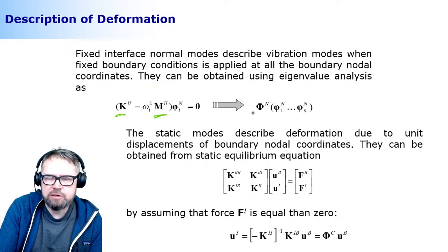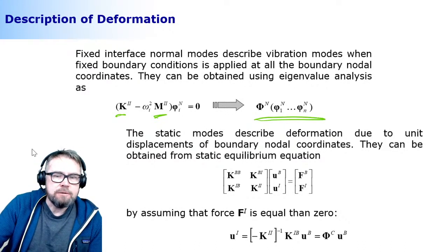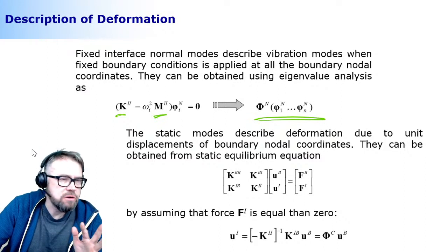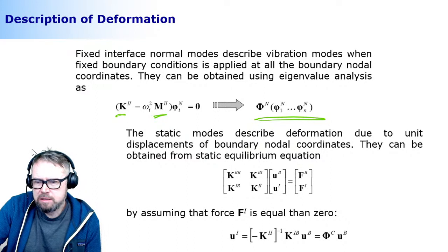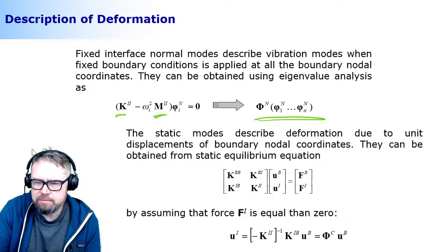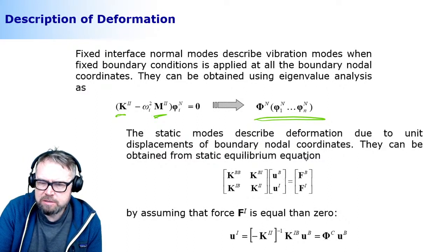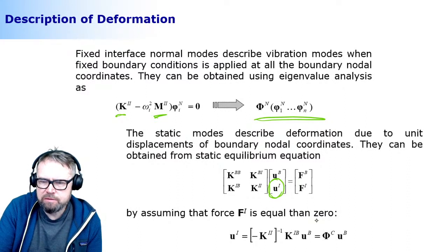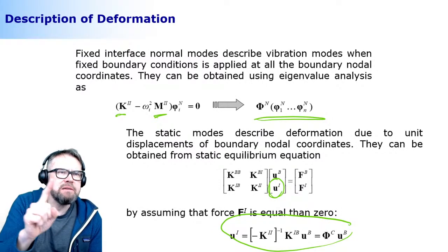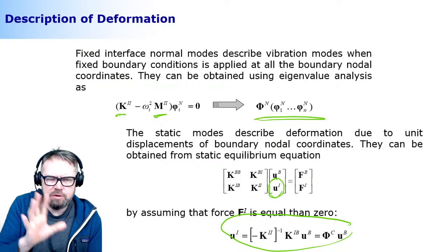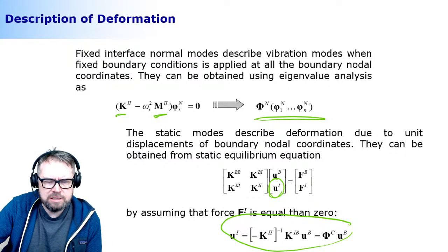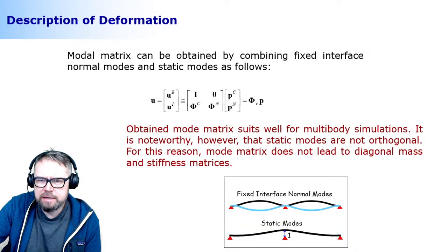Then you take your stiffness matrix, and from it you solve for these interior degrees of freedom. You get what are called static correction modes, which heavily emphasize this local deformation. I will give you drawings in a minute so you will see how they look.